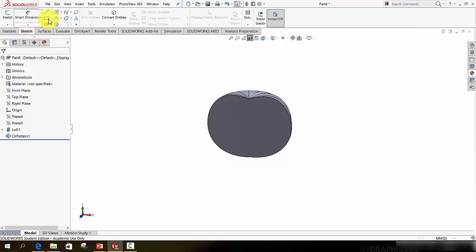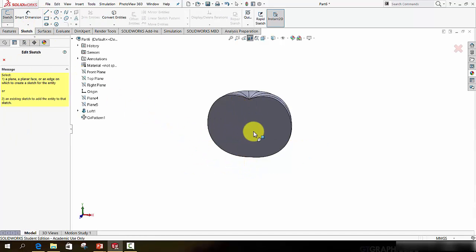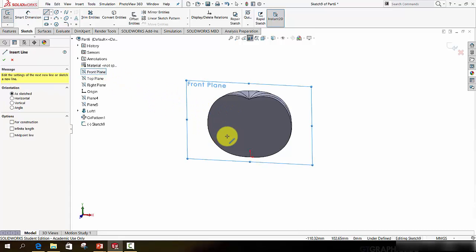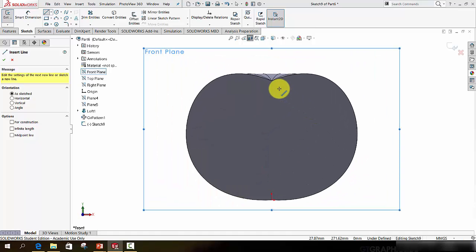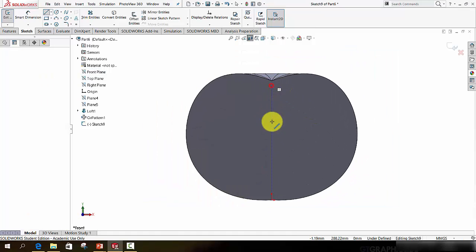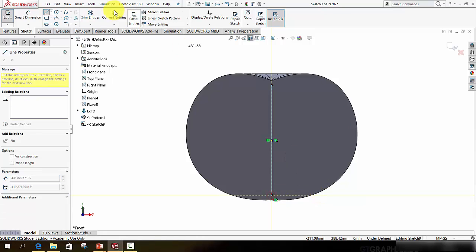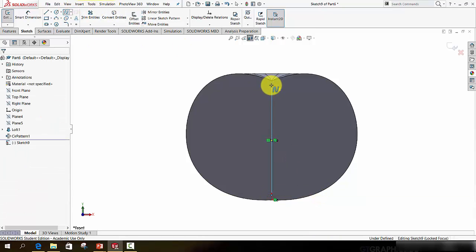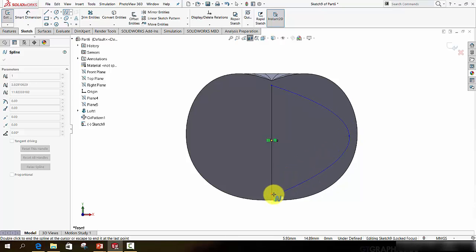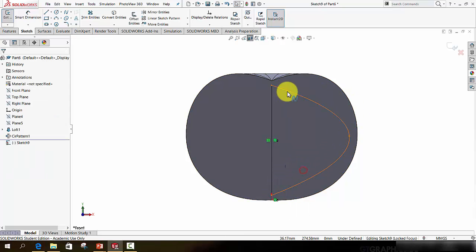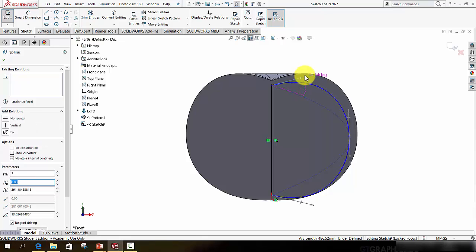I'm now going to start a sketch of a line. I cannot actually pick this face because that is just a theoretical split. That face doesn't actually exist, so I can't click that surface. Instead, click the front plane on which to draw. Hit the space bar, normal to, and take your time and just draw the profile that you want to use for the scooping out or the inner portion of the pumpkin. Now you need not be too fussy about that. It's not critical to the render or anything, but try to get it approximately offset from the outside.